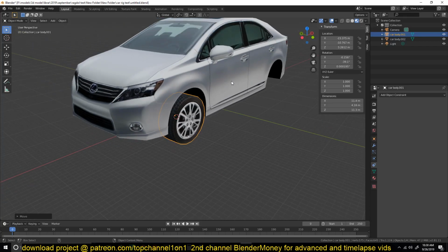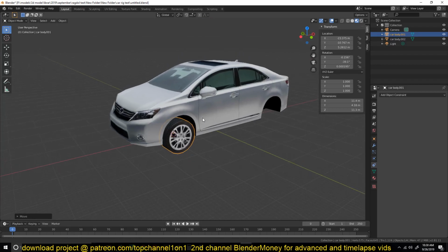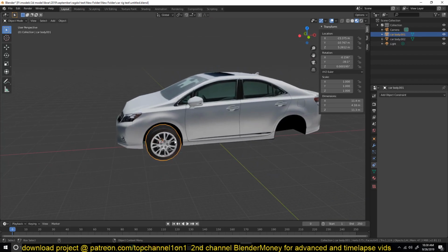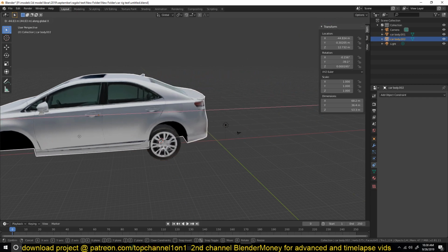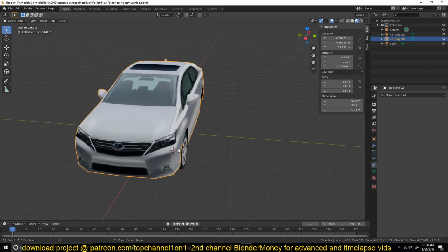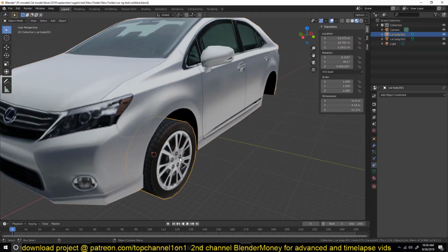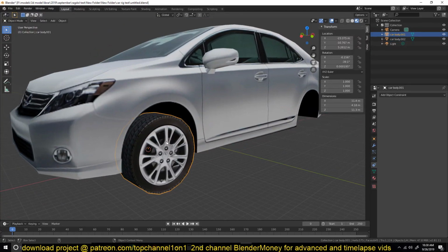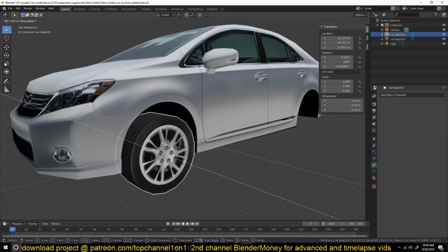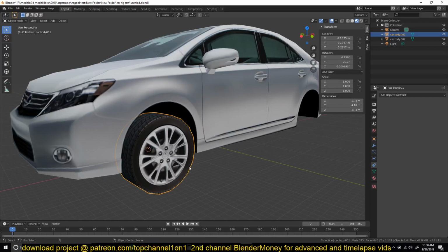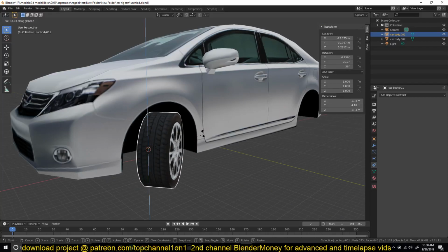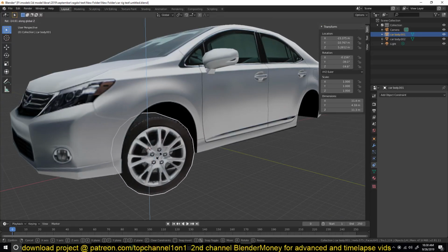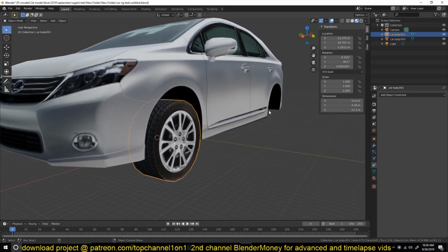So let's work on the rig. What we want to do is have this tire rotate on its y-axis whenever we move the chassis forward. And to make this simpler, we're going to separate the rotation of the tires in two parts. So we have the Y rotation, this is just moving forward and backwards, and we have Z rotation, that is making turns like this.